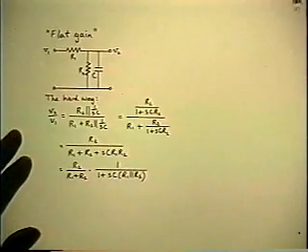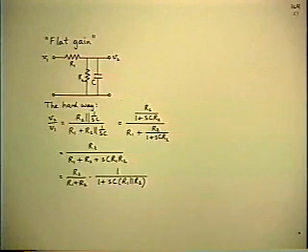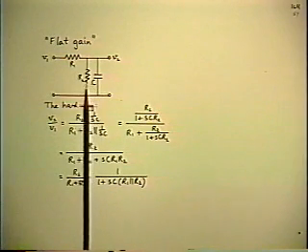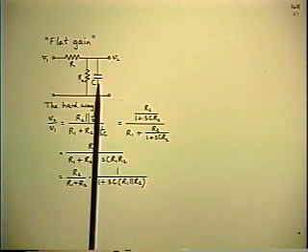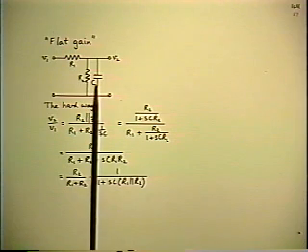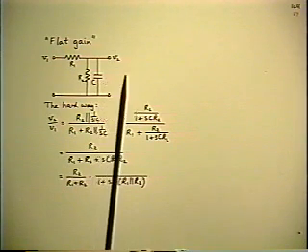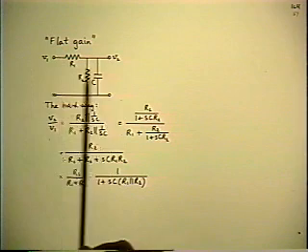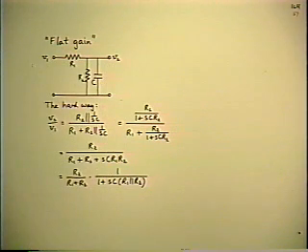Well, let's apply these low entropy ideas now to something a little different. We'll start talking about frequency response. So here's another very simple little circuit, passive circuit this time. 2 resistors and a capacitor. The objective is to find the voltage transfer function, V2 over V1.